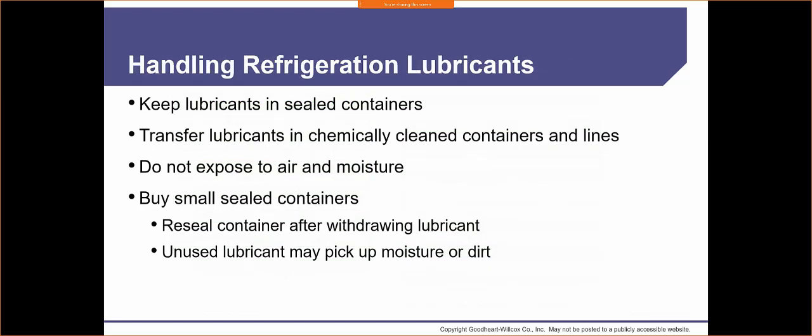All right, handling refrigerant lubricants. Keep lubricants in a sealed container. Transfer lubricants in chemically clean containers and lines. Do not expose to air and moisture. And buy small sealed containers. Reseal container after withdrawing lubricant. Unused lubricant may pick up moisture or dirt.